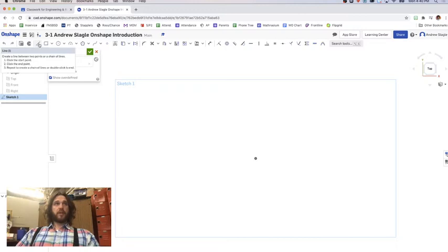I want you to grab the line tool. You'll notice when you hover over all these tools, there will be a little hotkey. So to make working in this program really smooth, you can grab the point or whatever you want. The line tool's hotkey is L. So when I'm drawing, I'm going to press L, and you will see that a little crosshair pops up.